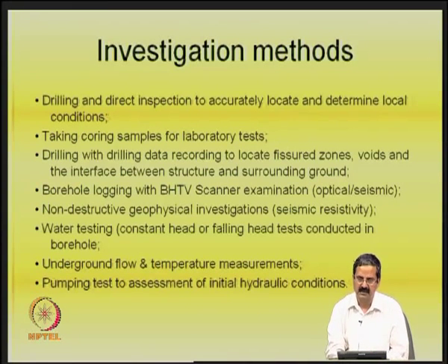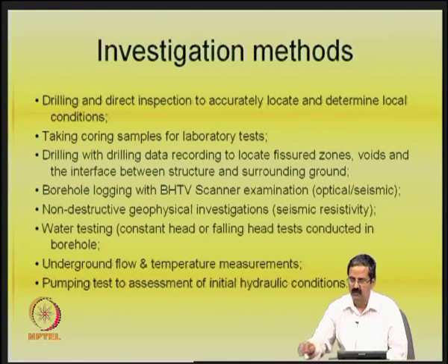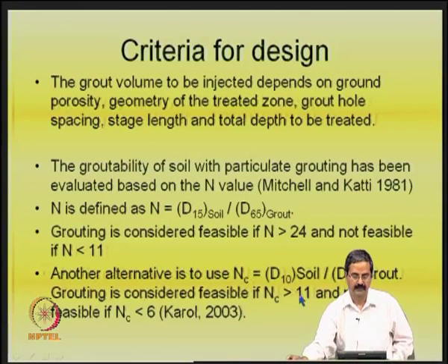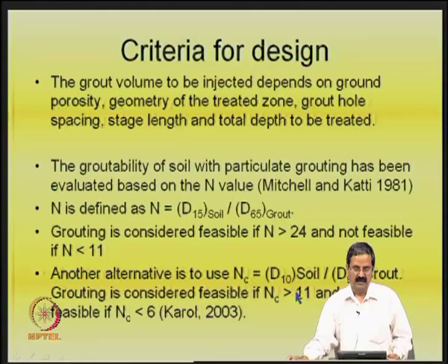So, temperature measurements are also important. Then pumping tests to assess the initial hydraulic conditions. As I just mentioned, grouting is very effective when the water table is there and all that. So, one needs to examine some of these conditions very carefully. The initial hydraulic conditions are to be known as well. There are certain design guidelines for how it can be done.